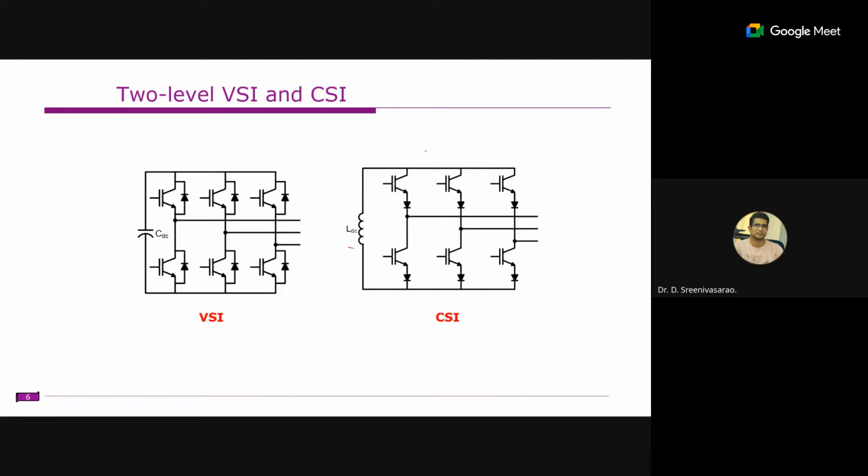So this can be overcome. We normally keep a 1 or 2 microsecond time delay, depending on your operating frequency. Typically, if it is a 1 kHz frequency, we normally use 1 microsecond. If your frequency is too high, in that case, the delay is in the order of a few nanoseconds.